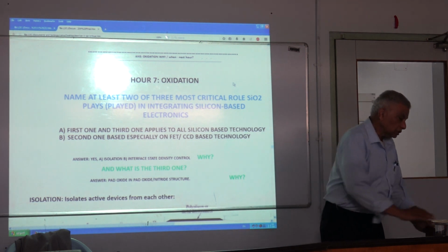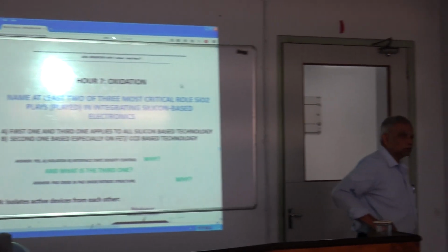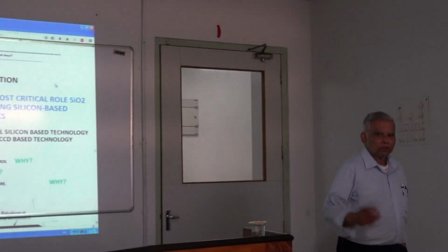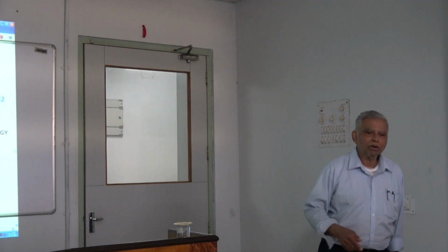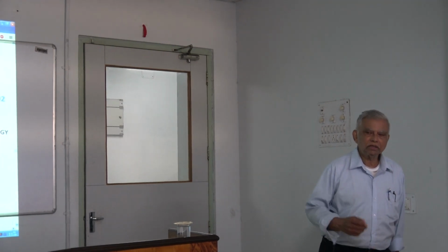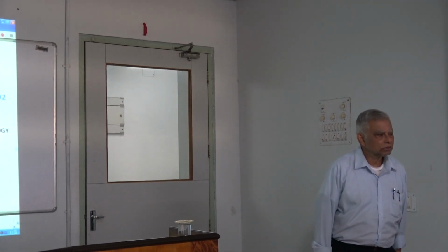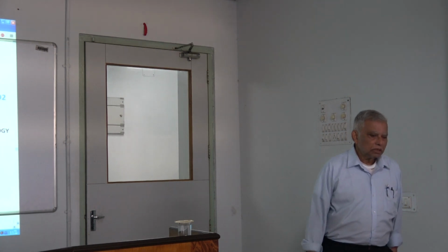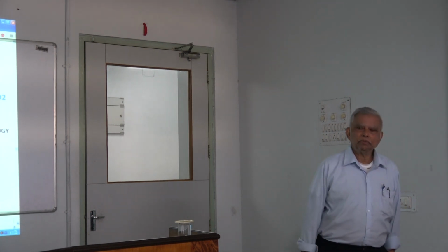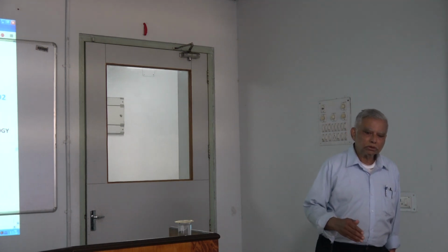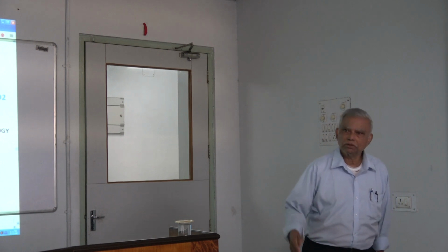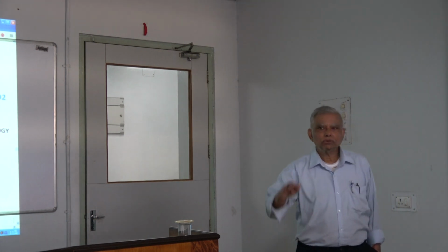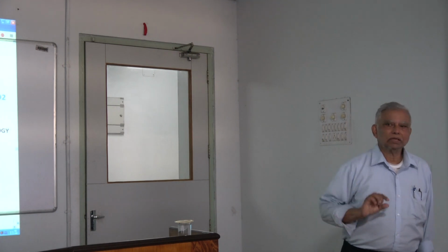The trap density in good quality oxide is extremely low. Trapping cross section is very large compared to nitride, which is far worse. But nitride has very good passivation characteristics. So the nitride oxide has been used for almost 1990 to 2000 plus as a way to scale the so-called gate oxide thickness down.